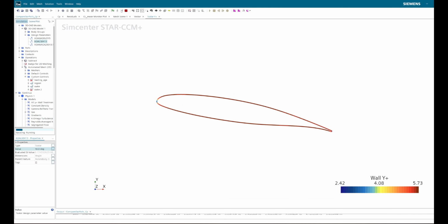In my setup, about 90% of all Y plus values are kept below 2, and the maximum Y plus is around 5. This indicates that my mesh and simulation settings can capture most of the fine details of the boundary layer very well, meaning the model is reasonably accurate and reliable.